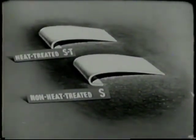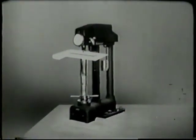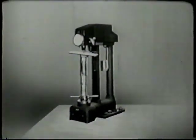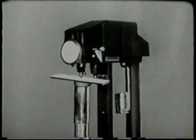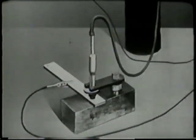The extent of change in physical properties may be judged by testing the aluminum alloy before heat treatment in the S condition and after heat treatment in the ST condition. One of these is a test for hardness, generally conducted on a Rockwell hardness tester. A penetrator is applied to the specimen with a fixed load, and the depth of penetration is taken as an indication of hardness.